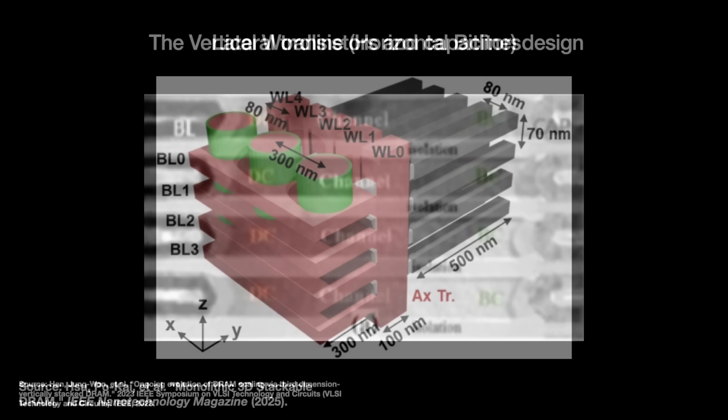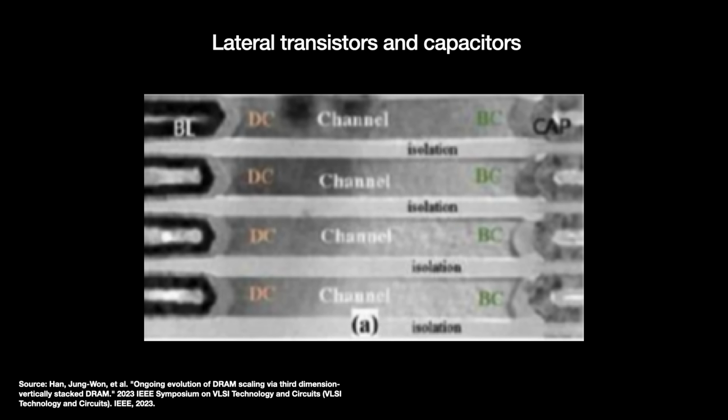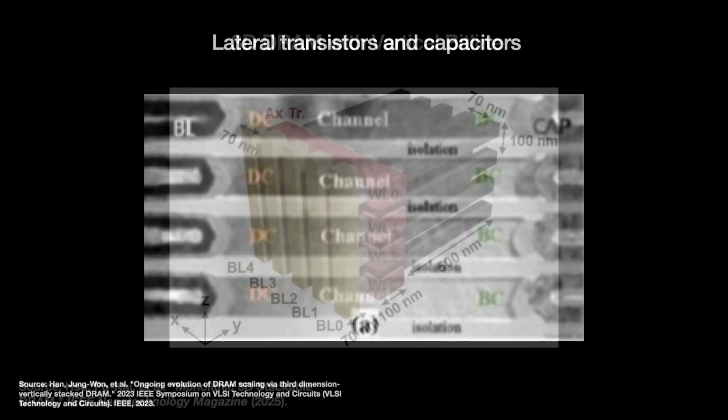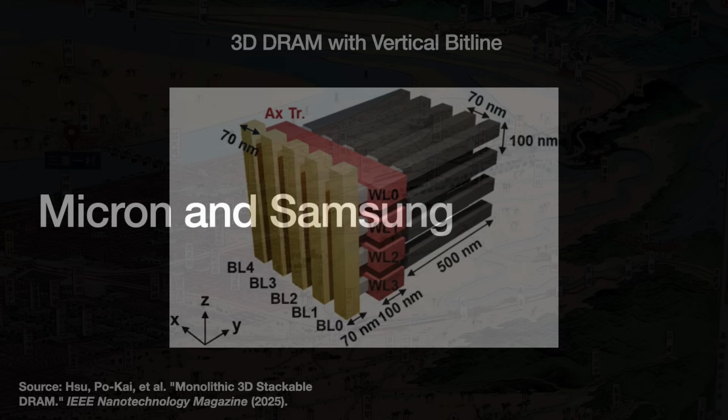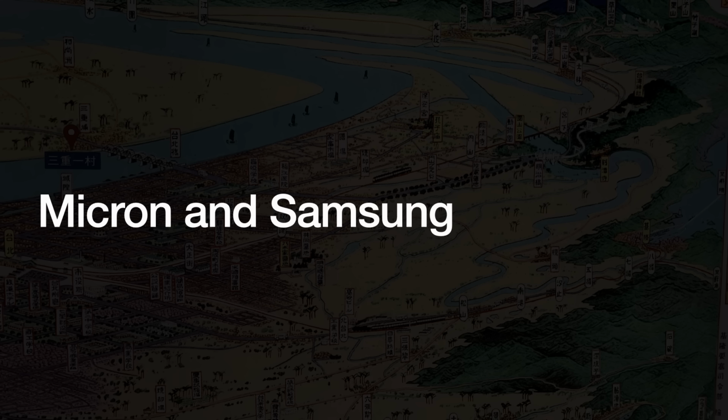Broadly speaking, industry people seem to hint that vertical bit line efforts offer more promise, a smaller physical footprint, and the bit line goes direct to the peripheral CMOS circuits. But we are not yet in full production, so things remain outstanding. We know that DRAM makers are working on variants of this, so let me cite a few examples.